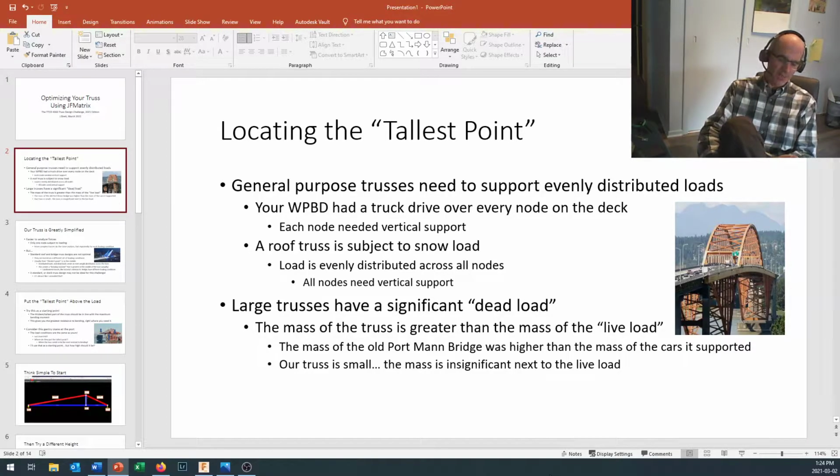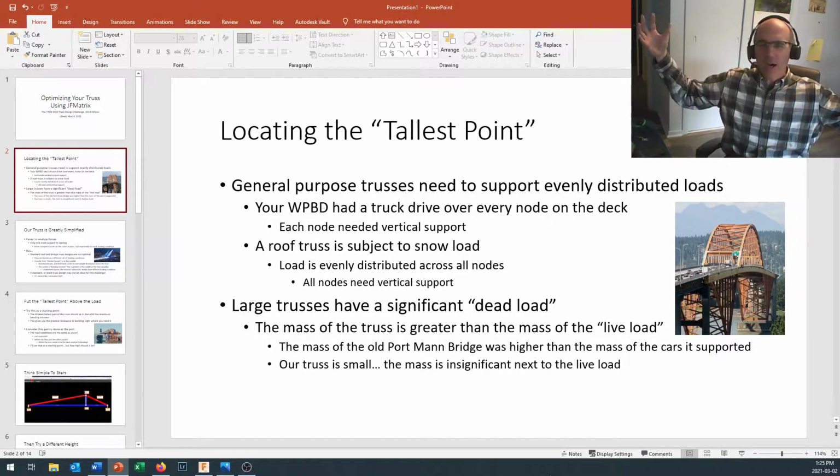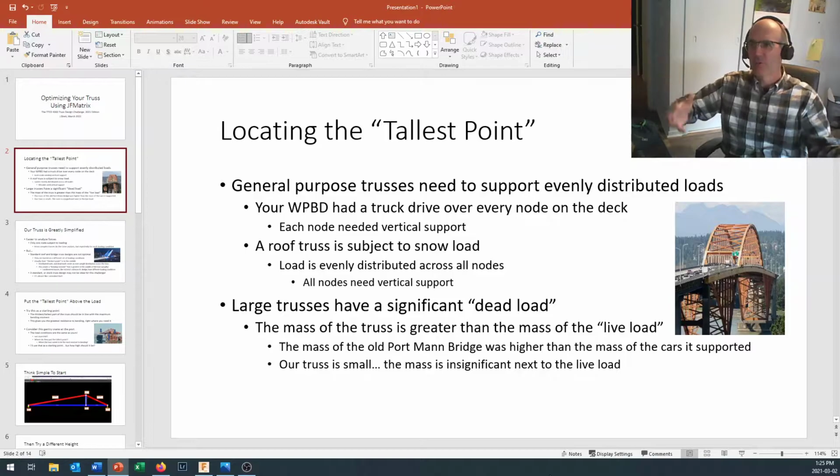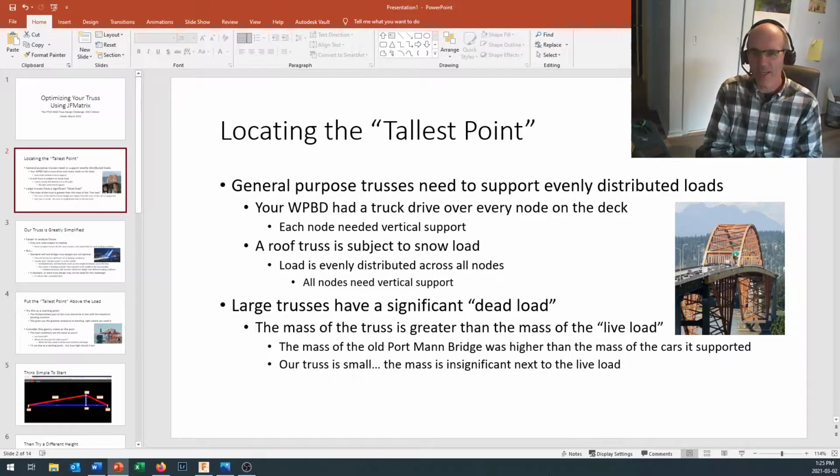They would only have increased in width and thickness, so their cross-sectional area would have increased only by a factor of 4, even though my weight increased by a factor of 8. So eventually, as you start scaling people up, you're going to run into a problem where the mass increase becomes too great for the cross-sectional area increase to support those loads.